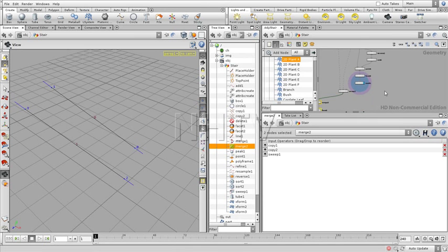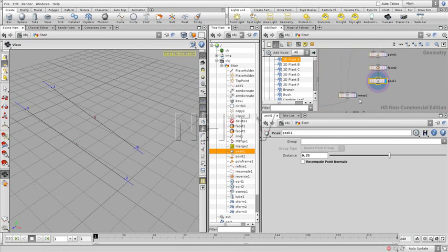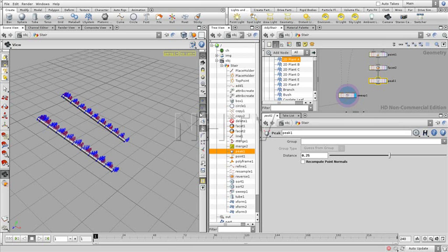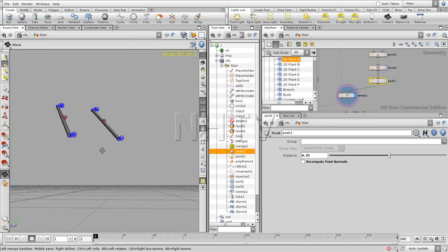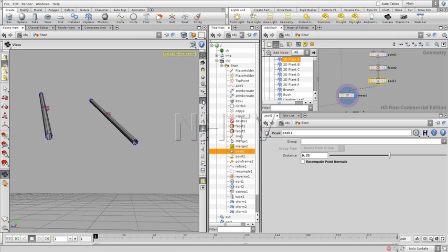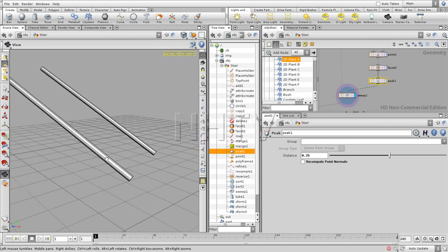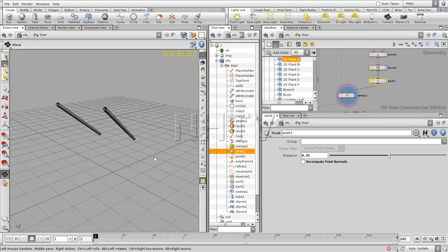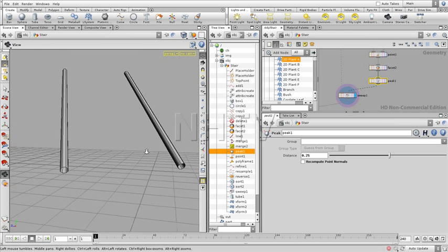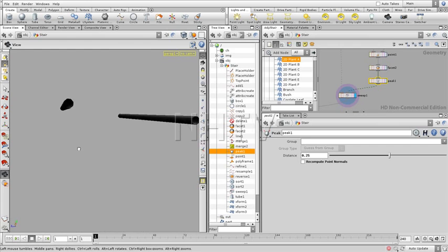So now we're going to use the result we have over here in the sweep node, and this is going to give us two things. First of all, it's going to make sure that all of these points that we're not going to use are being removed. And secondly, it's going to give us longer rails. So let's go over here and connect it. Right. Now the only thing we still need to do is end the caps over here. There are holes and we need to cap it.